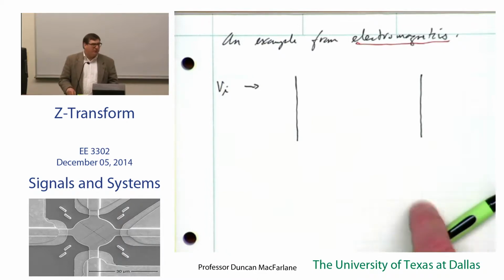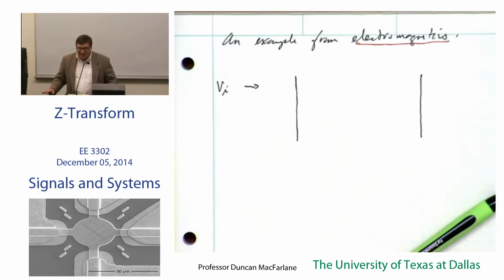And what we do in the lab, and eventually you'll realize how nice this is, but we take pains to make sure that the impedance between the signal generator and the transmission line and the oscilloscope, we make sure that those are friendly. Okay? So if we're working at very high frequencies, we have 50 ohms, 50 ohms, and 50 ohms, and that's a really nice impedance match. The world isn't always that way, right? There are 75 ohm cables out there. There are other wires on your circuit board that